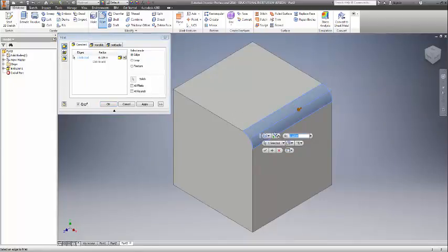You can make nice little curved edges on your edges. And it's asking me what's the radius. That R is asking for radius. And in this case I have 0.125. I'm going to select a radius of 0.75. I didn't hit enter yet, but as you can see, it gave me a little preview of what it'll look like. Okay, let's say I do a radius of 1.5.